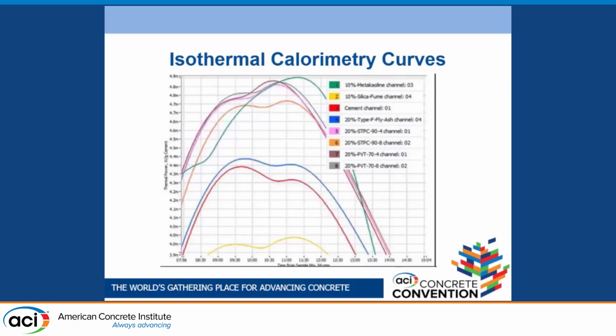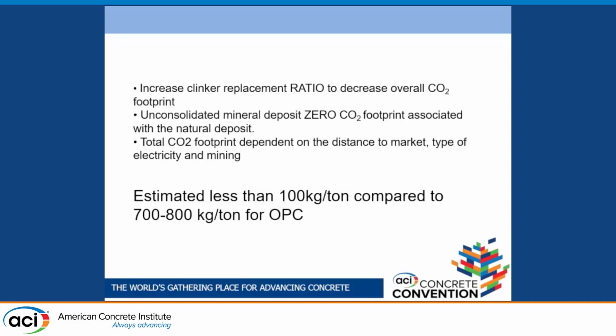And these are really blown up scales, so the silica fume looks like the instantaneous heat in the early days is a lot lower, but the scale is blown up to separate the two, and you can see the Metakaolin ends up being pretty high up on the top there, and the other ones are better than the cement and still give you a lot of heat coming off.